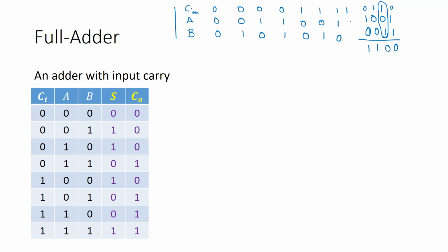So if I am able to understand the outputs of all these additions, then I will be able to form a truth table, and this is exactly what has been done in this particular truth table. You check out the addition now. Each set of 3 bits is added to get a sum bit and a carry out bit. This is the carry out.